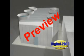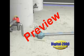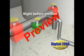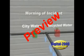The recycled water was supplied from several large outdoor tanks. The tanks were connected by wooden panels, forming a shed. A drain valve on the recycled water line discharged onto the ground inside the shed. On the night before the incident, this valve was left open to protect the water line from freezing. The next morning, the acetylene generator was started up using the city water supply.